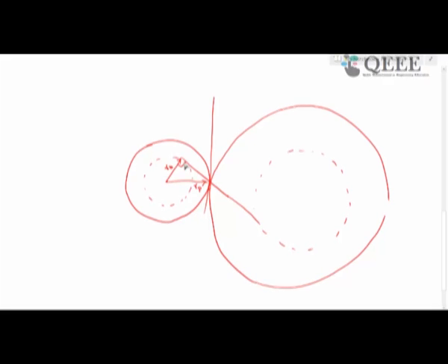So what happens is that this angle is phi, which is the pressure angle. This is also 90°. So that means this is 90 minus phi, which means this is also phi, right? Therefore you have a right angle triangle between RB and RP.